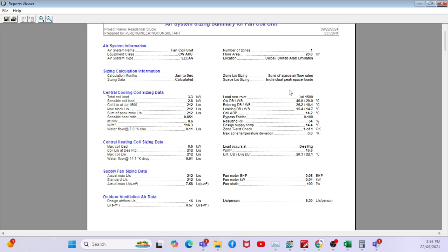Yes, this is the way we prepare our HAP calculation report. I request everyone to practice from your side. Take one of the rooms and start calculating the input data sheet, which consists of the total load: the lighting load, the equipment load, the number of people, the floor area, the height of the room, and the U value for the partition wall, external wall and roof.